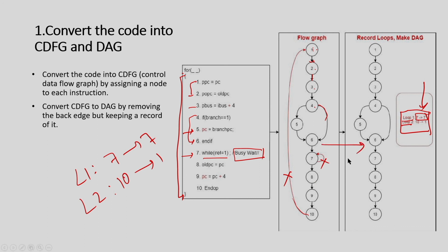So, this is done to avoid having an infinite number of paths, longest paths. Okay. If I have this, you will come here and then it will go on. So, it might have an infinite number of paths, right. Just to avoid that, I remove the back edge. Since I am starting my longest path again from the loop point, it will not create a problem, because eventually I know that this is the starting point, and from there if I add the back edge, whatever schedule I get, it will make sure that it actually happens in a loop. I am going to discuss these things in detail in a subsequent part, but let us assume that I am going to remove the back edge before identifying the longest path.